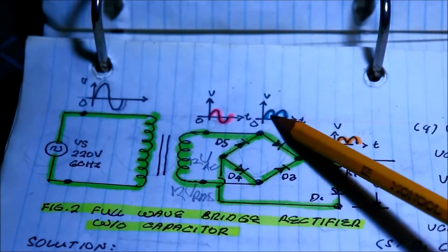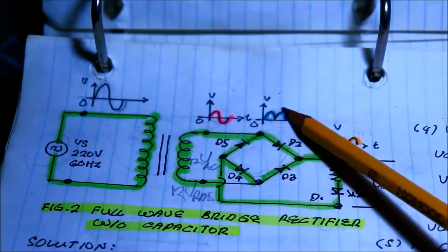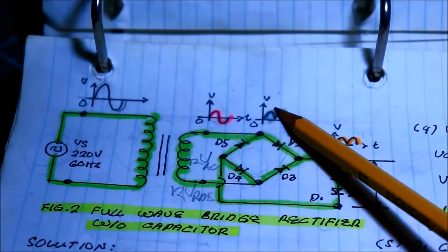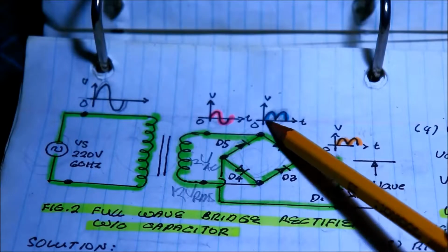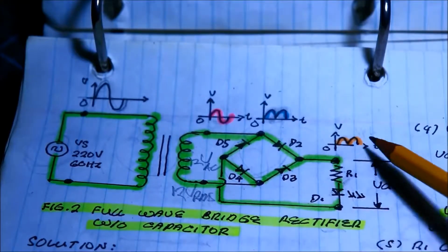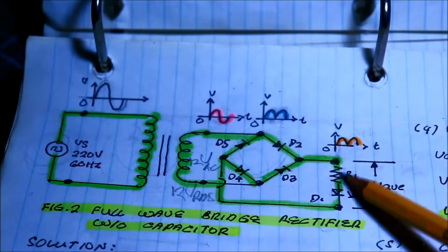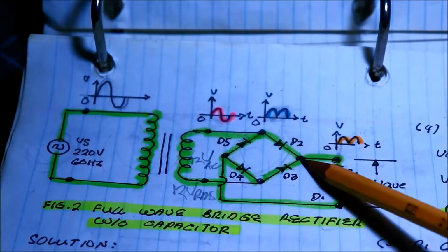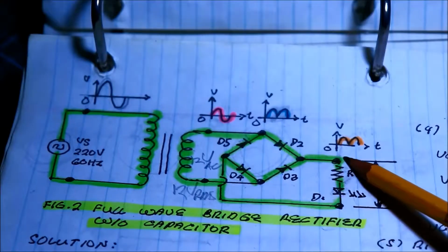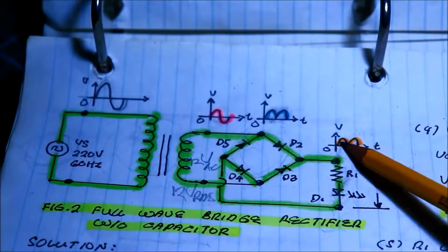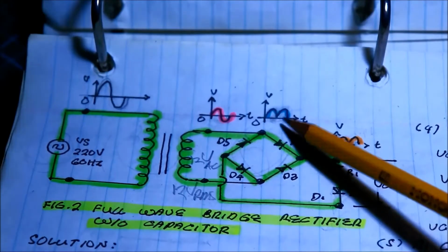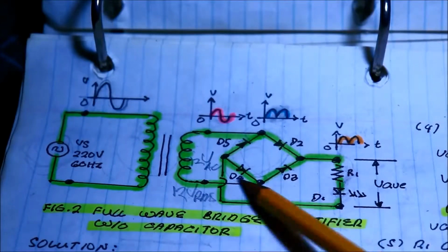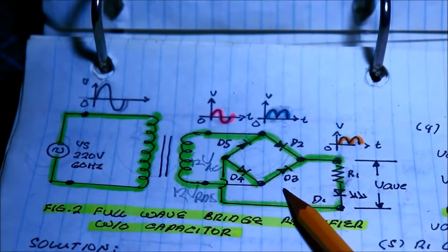To the rectifier, the rectified output is the two pulsating half cycles. These two output waveforms of the rectifier are also the same waveform output of the load, because the output of the rectifier will now supply the load, and this is the output waveform of the load, the same as the rectified output of the rectifier. We just disconnected the capacitor.